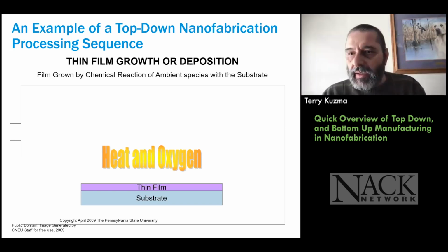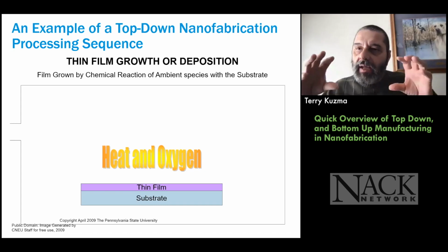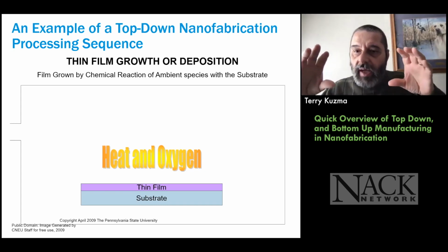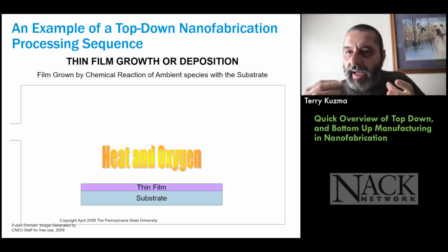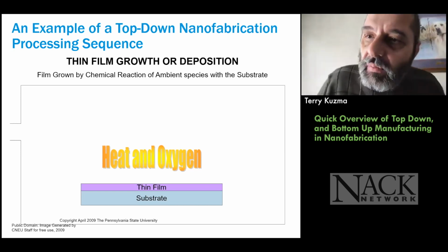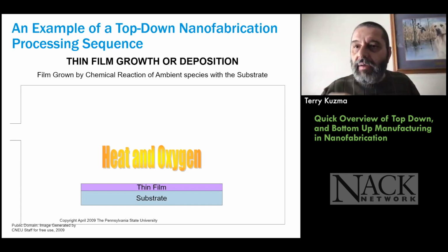The reason silicon is so important in the number one semiconductor is it has a native oxide, and it mechanically mates with the silicon rather well, and it doesn't delaminate, and it's inexpensive, and we can grow it by heat, we can deposit it, we can sputter it, we can do it by gas. There's all kinds of different ways that we can have an insulator.